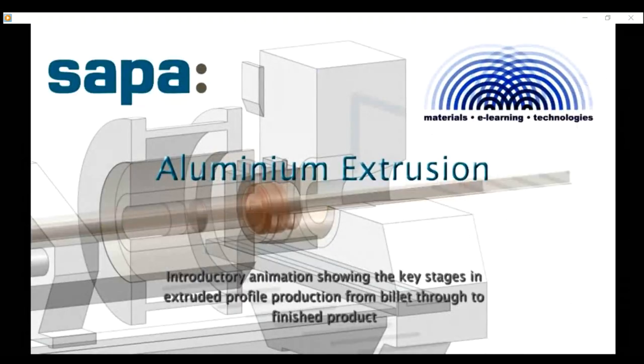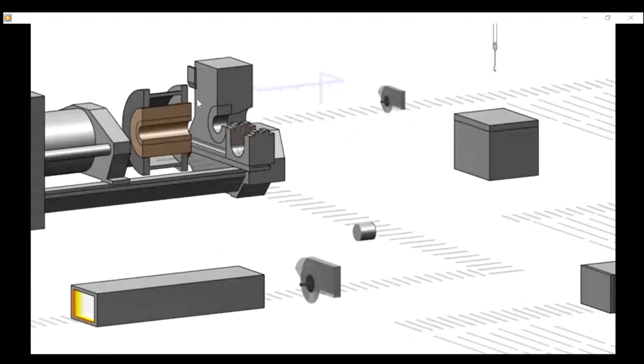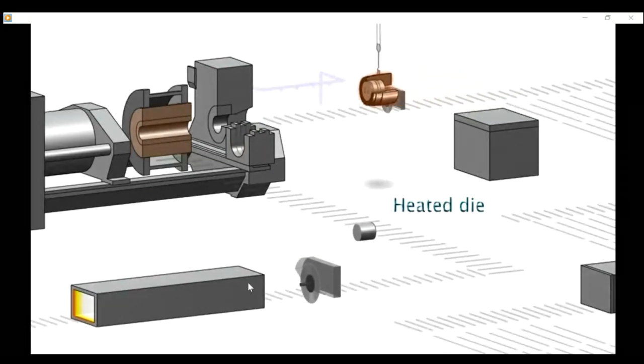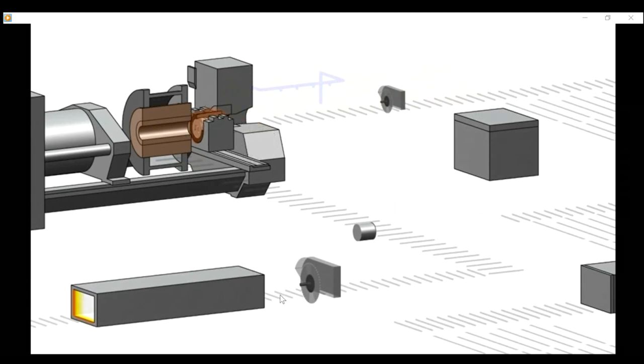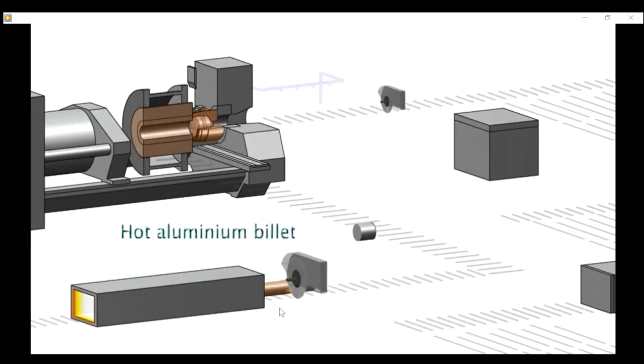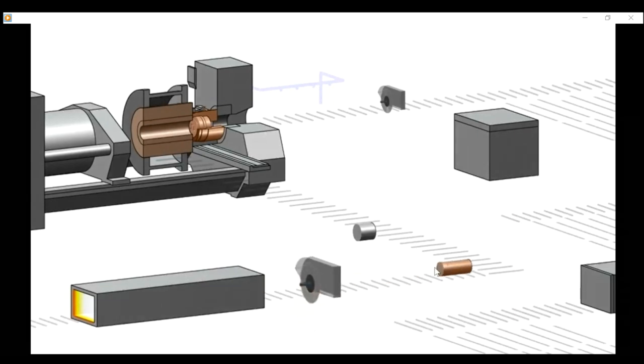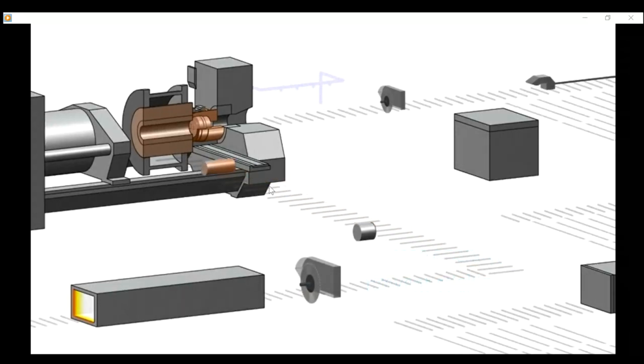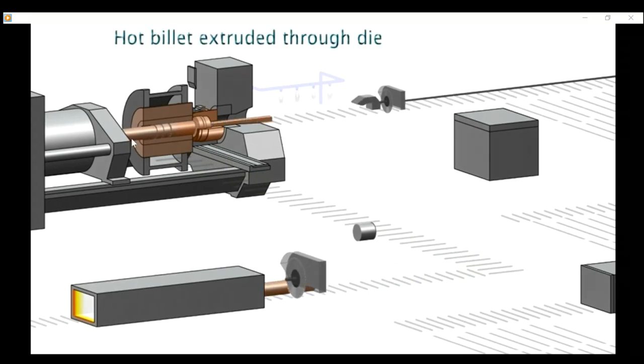This is the extrusion process, the extrusion machine. This is a pellet, the raw material. We put it in a furnace to make it a little bit soft. Maybe warm, maybe cold, sometimes hot. It depends on the dimension. This is in the furnace. It becomes hot enough, becomes soft. This is the part that we're going to extrude. This is the raw material, and there is some oiling. We put some oil to facilitate the motion. We put it here, and then this is the pressure.